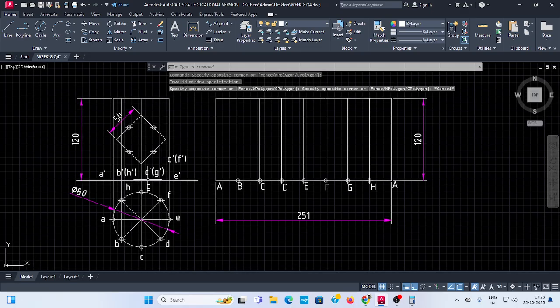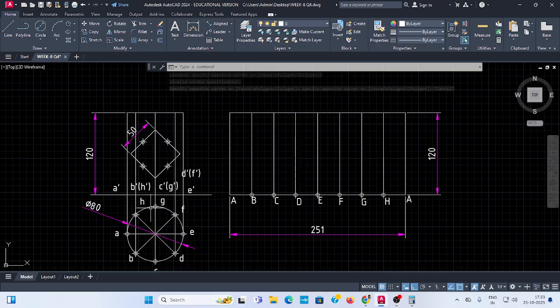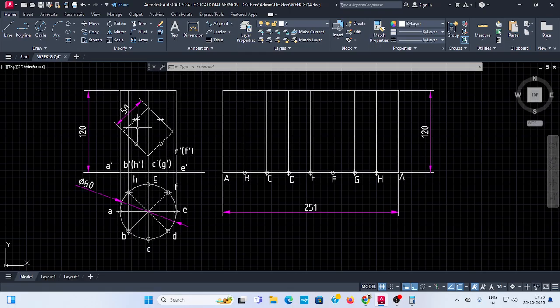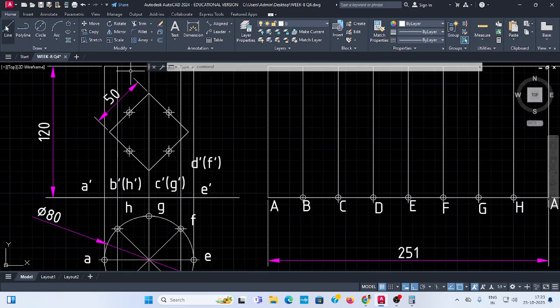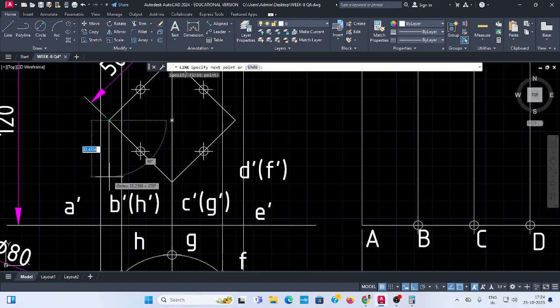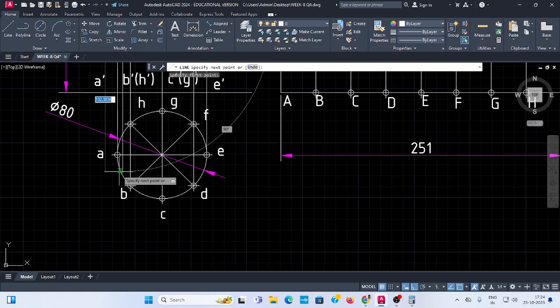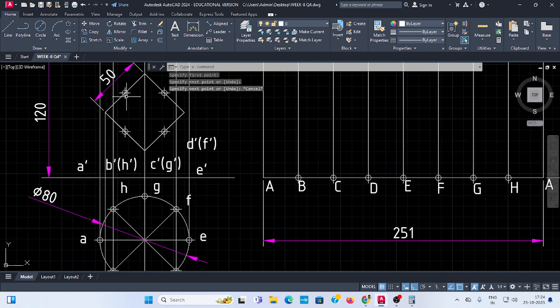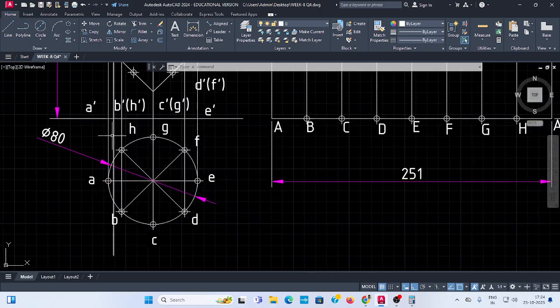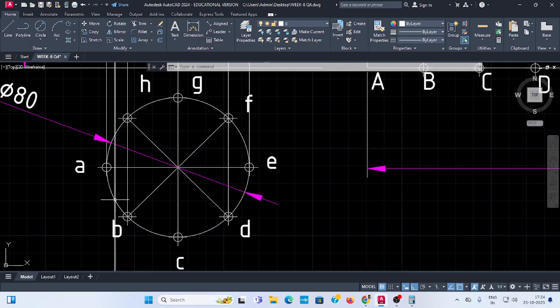Now this circular hole passing through the cylinder. So we are finding out this. This corner, 1, 2, 3, 4. Okay. The first corner I project up to the downside of the cylinder. The first circular hole, this corner point I pass through with a line. This cuts the cylinder here. Okay. From the center draw one line here.